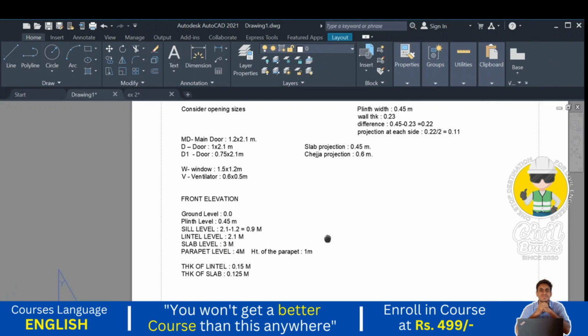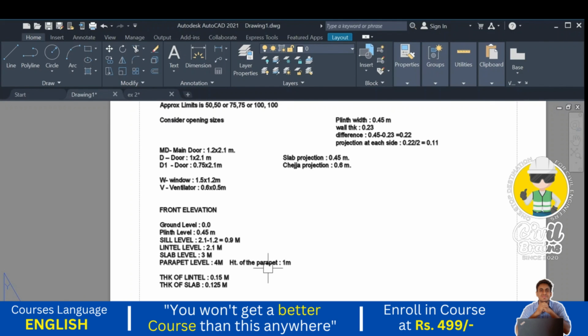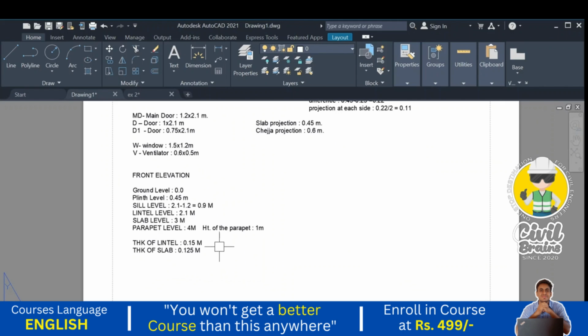Okay, these are the standard thicknesses which we provide for residential buildings. For other buildings it will vary, and the thickness of the lintel also depends upon the width of the window. But the width of the window is smaller here, that is 1.5 meters, so no issue. 0.15 meter is enough.